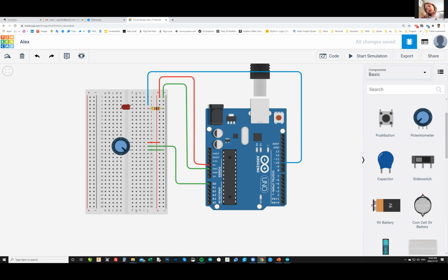Do I need to put the thing that we did last lesson back in? I was a little late. You will need to assemble it like I show right now on the screen, with an LED and 1 resistor. The LED leg goes into pin 10, and then we will have the potentiometer going to A0.